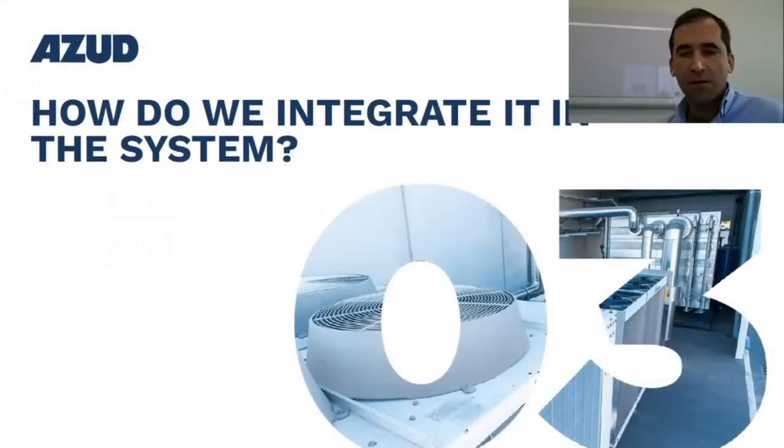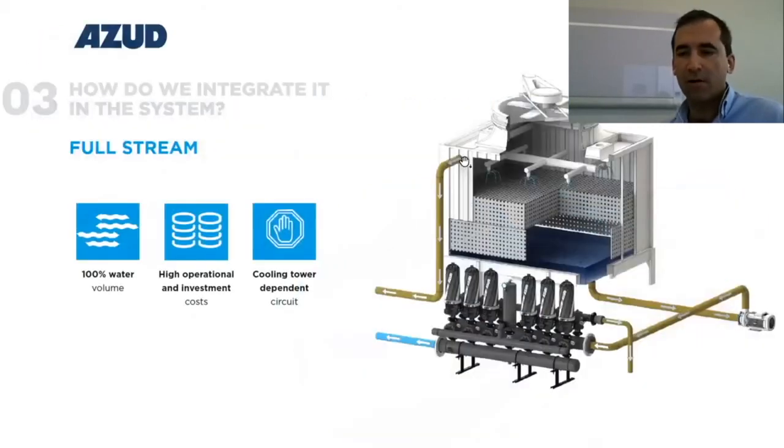How do we install a filtration system? We have two options. Mainly, the first one is full stream. The full flow filtration uses a filter installed after the cooling tower on the discharge side of the pump. So the filter continuously filters all the recirculating water in the system, and the filter must be sized to handle the complete flow rate.